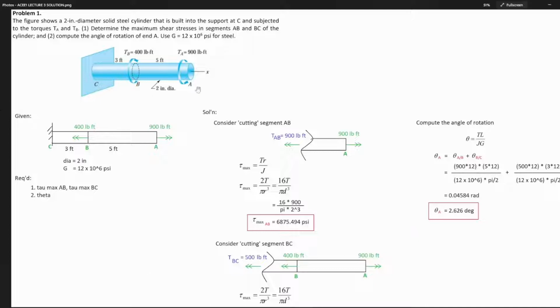Okay, so this is our figure. It's 3D, no? You have a counterclockwise torque at A, a clockwise torque at B. Now, referring to the right-hand rule, let's look at the torque at A. When you apply the right-hand rule, your thumb will be directed to the right, no?